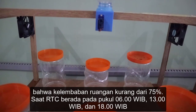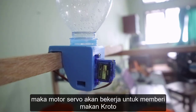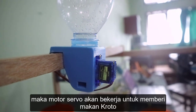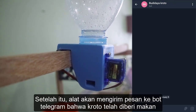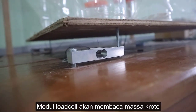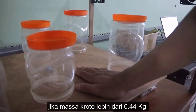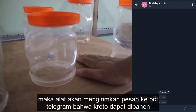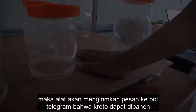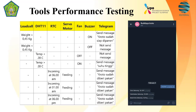When the RTC is at 6 AM, 1 PM, and 6 PM, the servo motor will work to feed croto. After that, the tool will send a message to the Telegram bot that croto has been fed. The load cell module will read the croto mass. If the croto mass is more than 0.44 kg, it will send a message to the Telegram bot that croto can be harvested. The next is the result of overall performance testing.